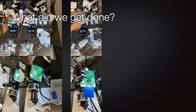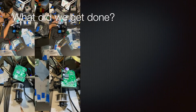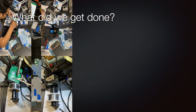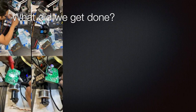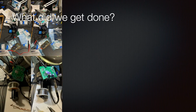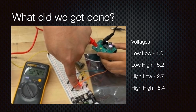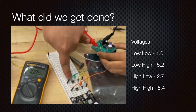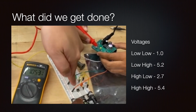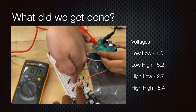Next, how did we test what we have built so far? We tested our PCB by measuring the voltage at where the lamp would be. We injected a 3.3 volt high on our 2 input pins, and the voltage at the lamp measured the following.